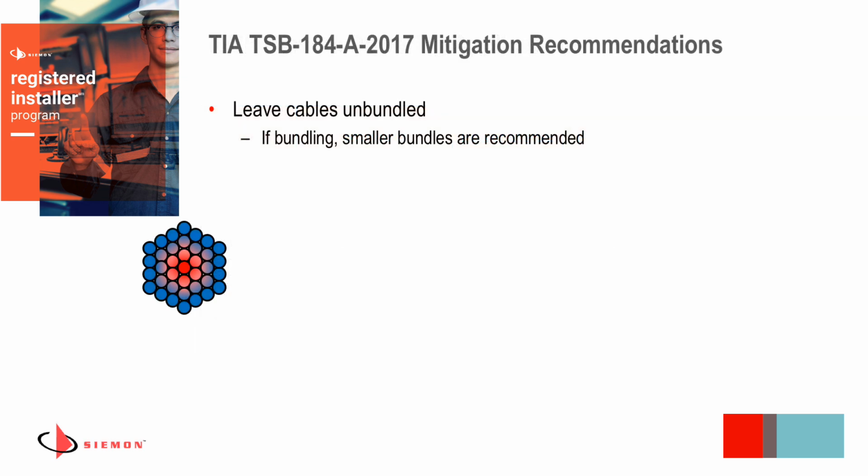In 2017, TIA released a technical service bulletin, a TSB, which is kind of an informational standard, if you will. So it's not mandatory, it's just a best practices type of standard. It talked about mitigation recommendations for managing large bundles of cables as a study. Historically, installers will tend to use larger bundles and really want to manage them well all the way from the work area locations into the telecommunications room. But the reality is that bundling cables perfectly can have detrimental effects on the cables in the center of those large bundles.